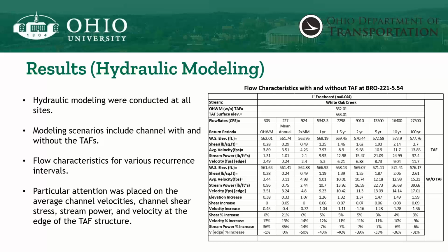Anyways, for this site, we first compute using twice the max monthly flow, right? We already know the design flow rate for this type. From StreamStats, you can actually get the 2-year, 5-year, 10-year, 100-year, right? To get these flow elevations. So these are all HEC-RAS results.